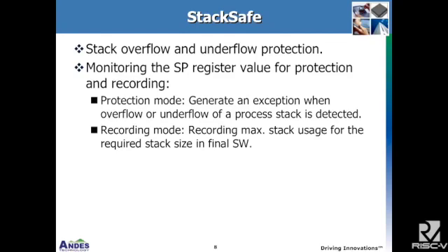And another use is for recording. In the protection mode, if the process stack is overflowed or underflowed, the hardware will generate an exception. And in the recording mode, actually, a lot of customers need that because when the system runs, you really don't know how big your stack is. With that mechanism, you can record the maximum stack usage for your applications.